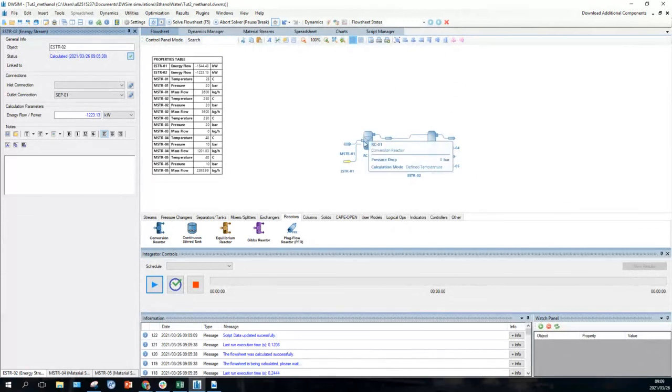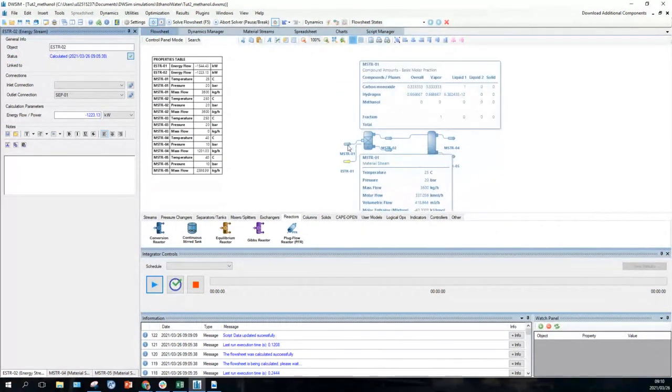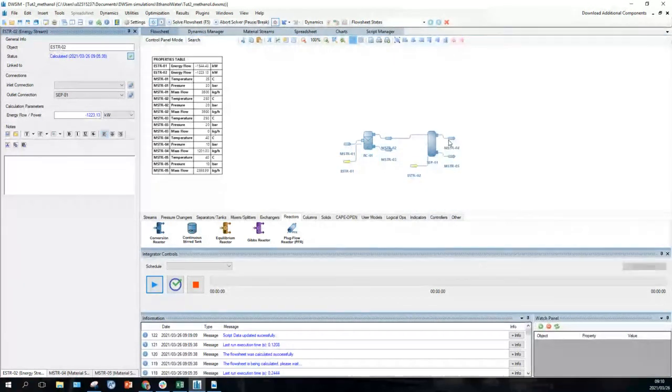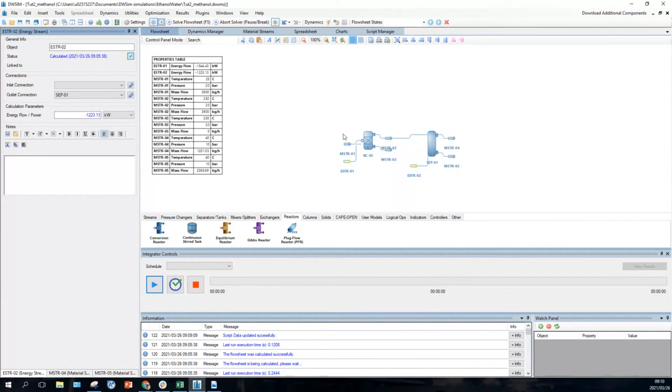You can confuse your simulation because, remember when we put in the hydrogen and the carbon monoxide here, we used 0.3334 and 0.6660, and because of that slight difference in the stoichiometry, if we recycle this totally without having a purge, we're going to build up one of those two. We're going to build up the CO in the system, and your thing is not going to solve. So it is important to first put this through a splitter, and then you can recycle most.